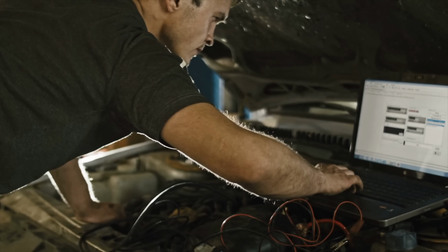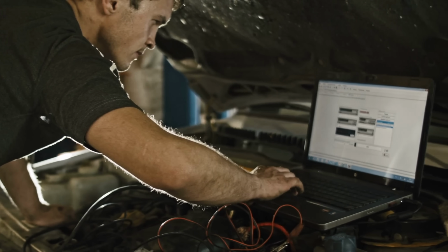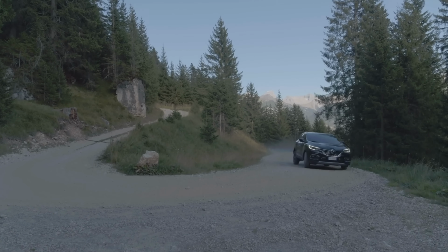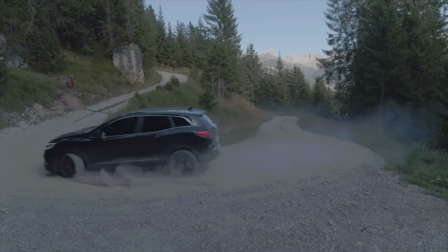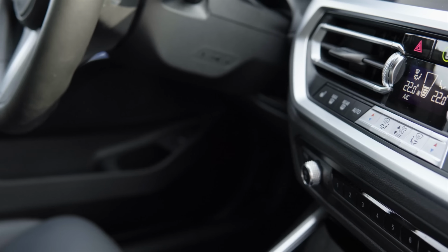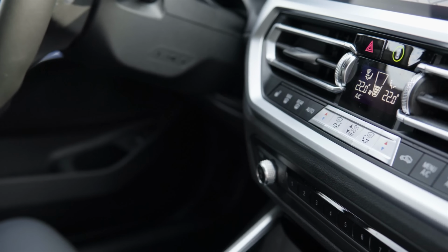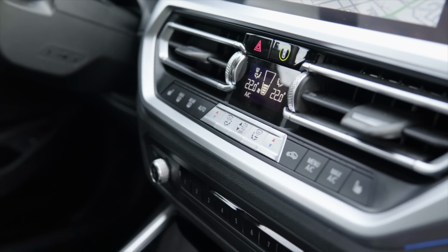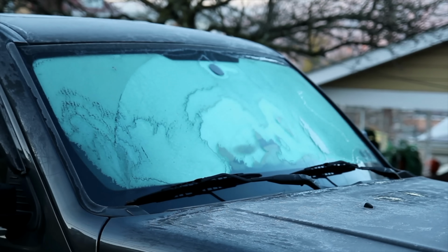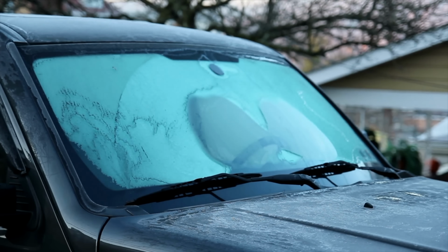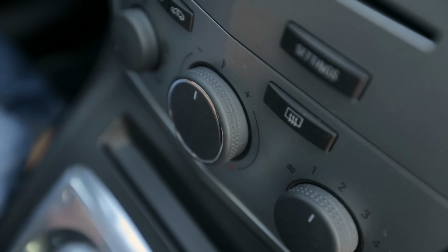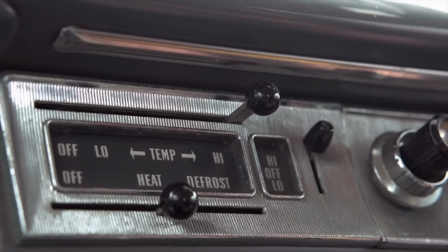That's why regular maintenance can go a long way in extending the life of your car's air conditioner. So here are a few helpful tips on how to extend the life of your AC. For starters, turn on the air conditioner in the winter. It wicks humidity away from the interior of your vehicle. But don't worry, in most cars you don't even have to do that. When you put the defrost on, it automatically turns the air conditioner on in most modern cars when the heat's on and defrost is turned on. This will also help to reduce windshield fog for better visibility.